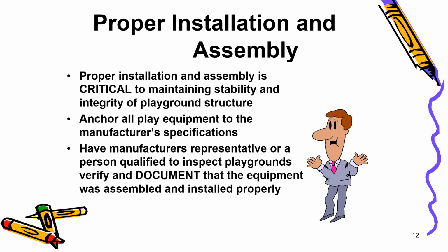Proper installation and assembly is critical in maintaining stability and integrity of playground structures. Make sure you anchor all play equipment to the manufacturer's specifications. Have a manufacturer's representative or a person qualified to inspect playgrounds verify and document that the equipment was assembled and installed properly. Equipment not installed or assembled properly is not safe.